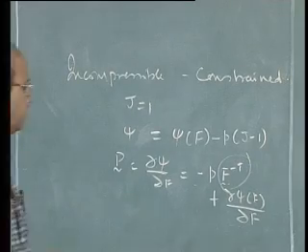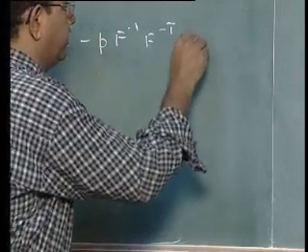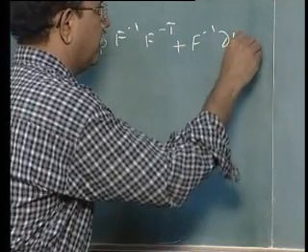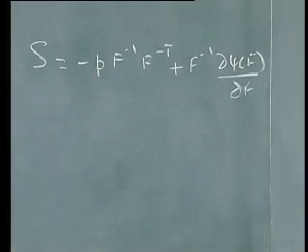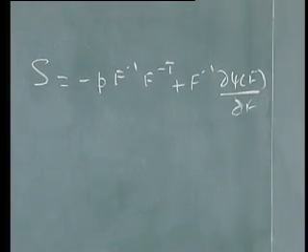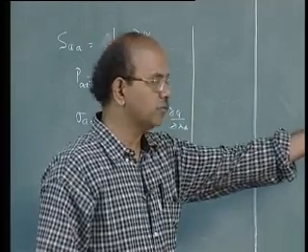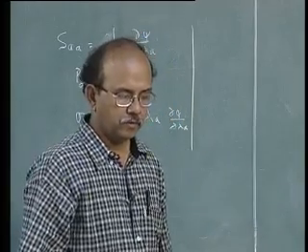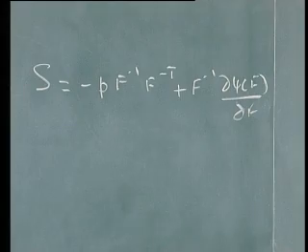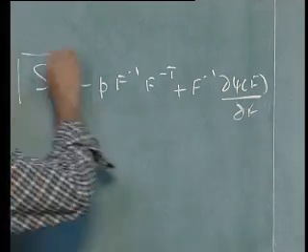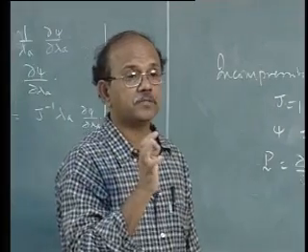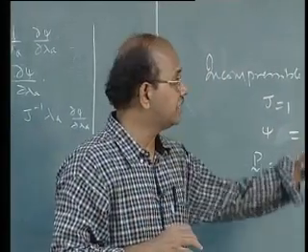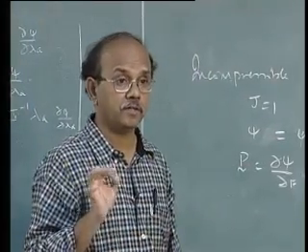Okay, so plus F inverse dou psi by dou F. Go back and refer to the relationship between P and S. In this case it becomes S is equal to F inverse P. Then that's the second one. It's a very important relationship. So these are again general relationships for incompressible material.